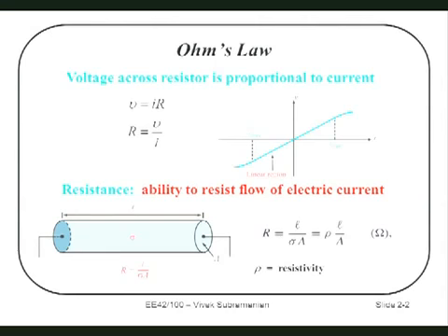Okay, what do you think the units are of resistivity? You can get it right from that equation. What are the units of resistivity? Yeah. Not per square, you're getting close. Yeah, it's ohm length: ohm meter or ohm cm. Because remember, you're multiplying by length to the 1 and dividing by length to the 2, which means this has to be in units of ohm times length, such that the final answer comes out in ohms. Okay, good. So that's how we define resistivity.